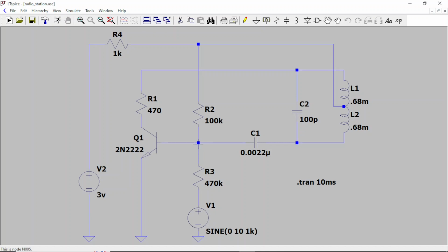Usually in an AM transmitter like this, the audio frequency signal is fed probably in the collector, somewhere in the collector. You get the amplitude modulation by varying the voltage supply to the collector. But here it's different, and that's what makes this circuit a little bit interesting.